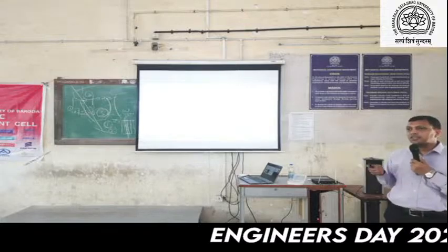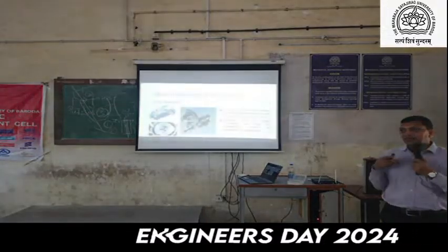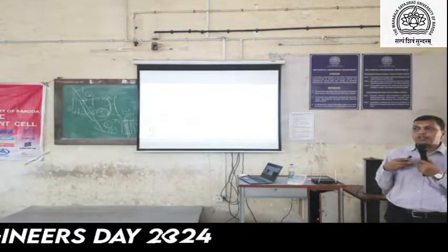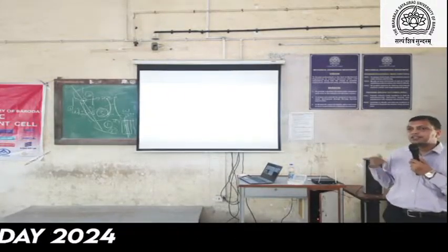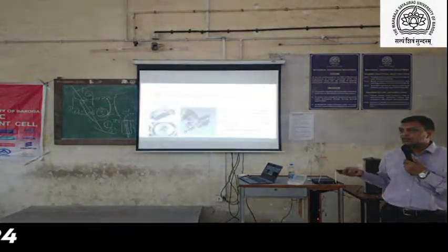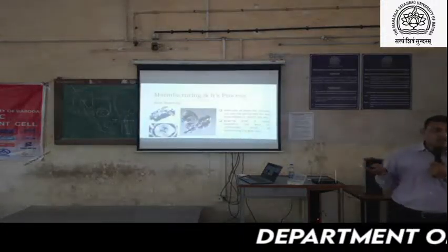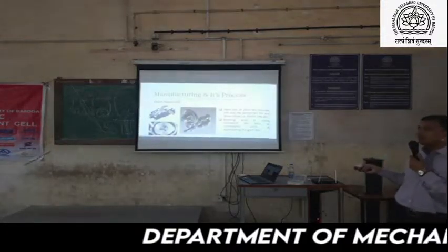But in taper roller, there are two parts fitted at the time of assembly. If we preload that, it will generate a temperature issue. So that should be controlled during the assembly, and that is the axial play we have to maintain.